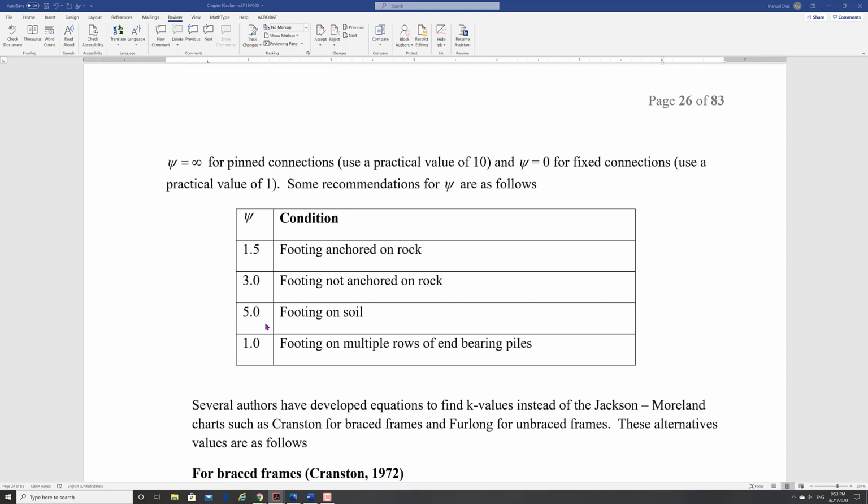What kind of curvature do you have? It's a single curvature. So making it a pin connection at the footing, with only one moment at the other end, is kind of the worst condition for this column: large moment, single curvature. So you're being conservative in your design.